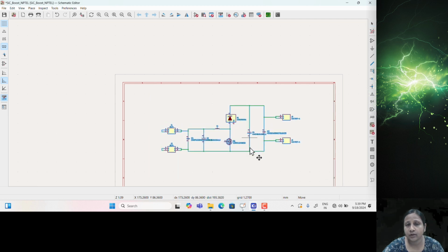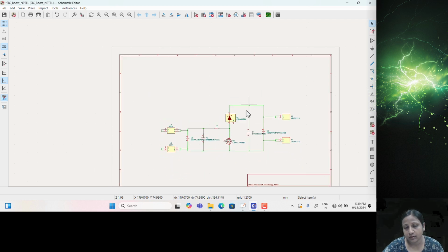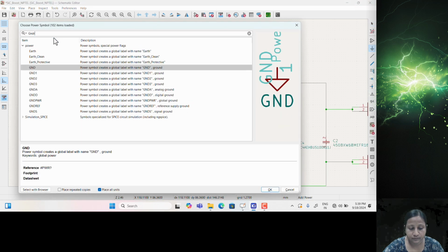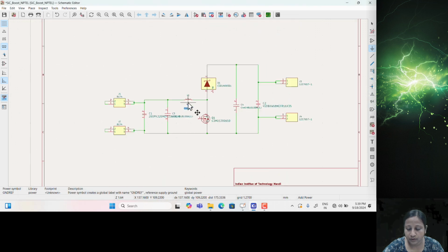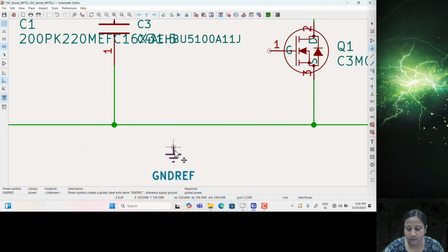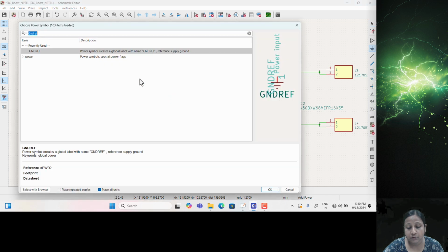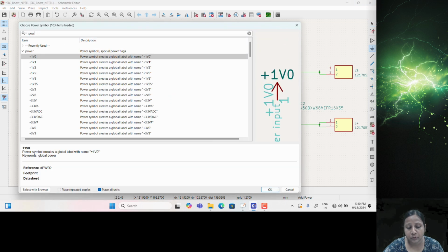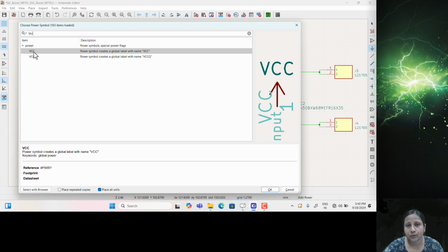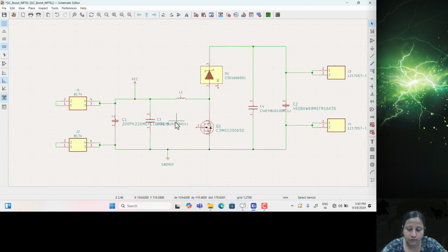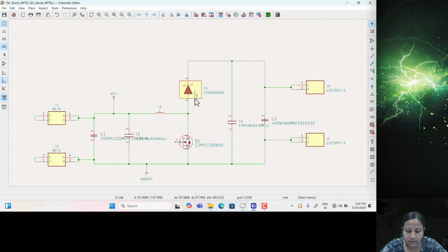So the whole system schematic is now complete. So this is the boost converter, right? One more thing here is that you need to connect the ground reference. Sometimes the ground reference is the negative terminal, sometimes it may not be the negative terminal. In that case you have to connect it separately wherever the ground connection will be. As I have discussed during the EMI discussion, the actual ground is different. So here you have to connect the positive and the ground terminal. Okay.